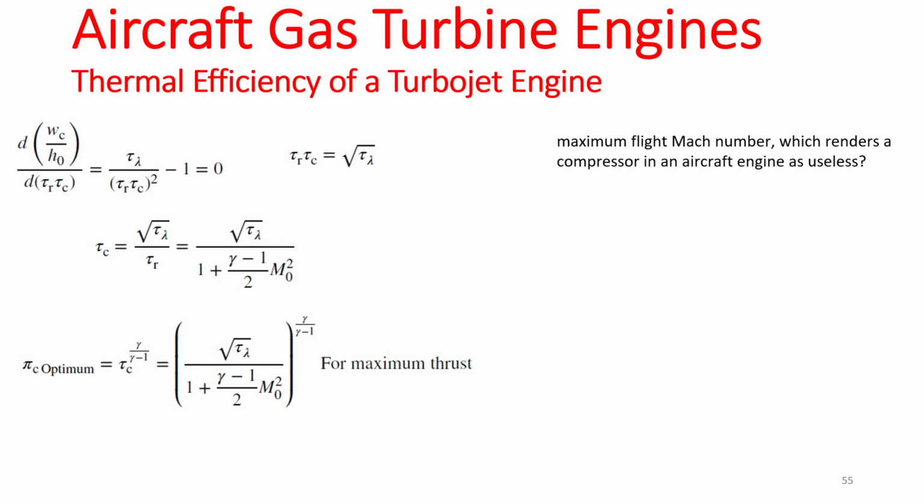But when you get to Mach 2, Mach 3, what's happening is that your aircraft is already flying, right? And even if you turn off the compressor or change the engine to a ramjet, your performance may take a hit because you have removed the compressor from the equation, which means that the pressure you're giving to the turbine is not as compressed as it should be, right?